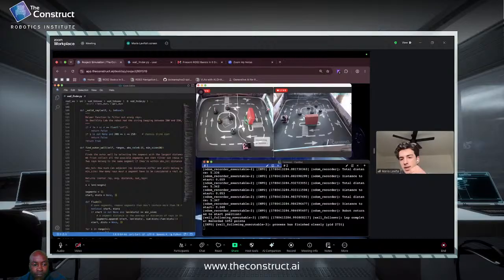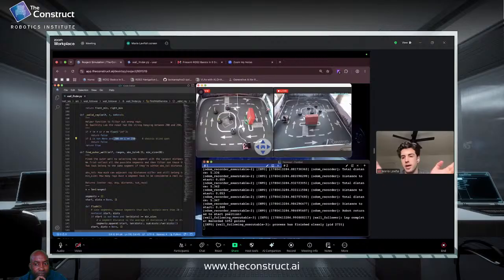The problem with this is, as you can see at the top of the robot, we have the laser scanner. What happens here is if we're deciding most of our actions based on minimum distance, just to understand where the obstacle is closest, what can happen sometimes is that the robot picks up this pole, this stick, as the minimum distance. So one thing that I made sure is that, when looking at a series of rays, I always exclude the 200 to 250, which are the rays that encompass that pole, in order to exclude that from my calculations.